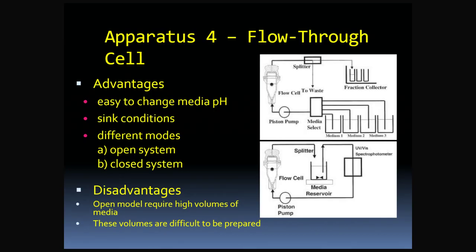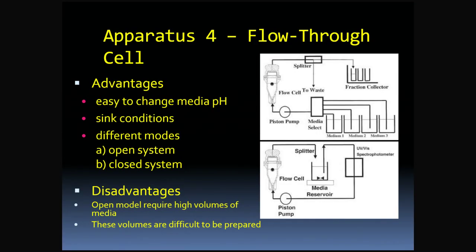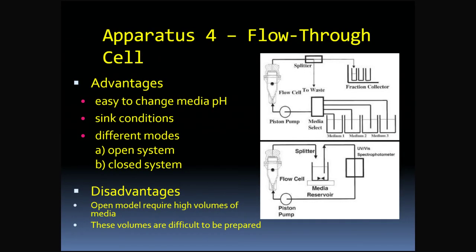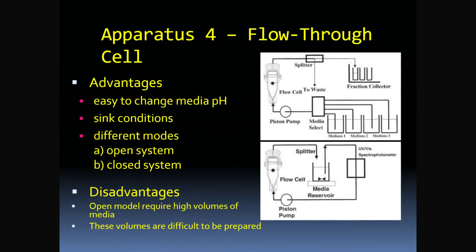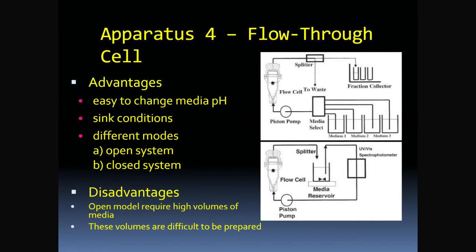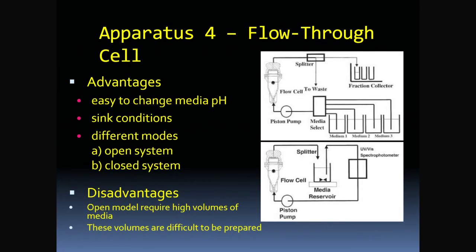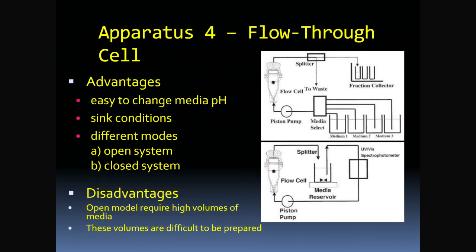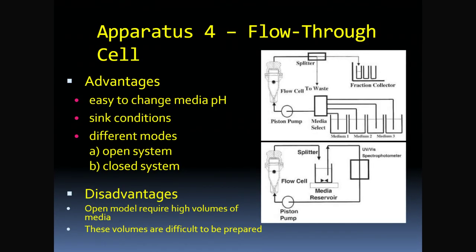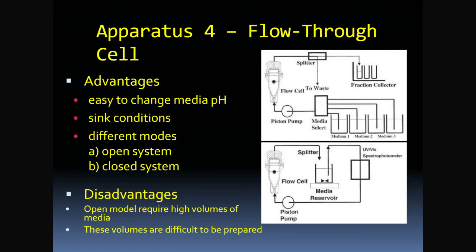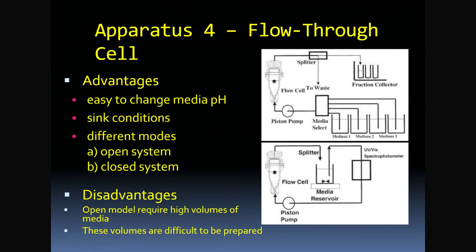In the open configuration, the continuous introduction of fresh solvent ensures that the concentration gradient, the mathematical difference between the drug's solubility limit and its current bulk concentration, remains at a theoretical maximum, essentially eliminating the risk of saturation. Notice the integration of the media select valve. This engineering feature enables precise, instantaneous pH transitions to simulate the sequential movement through the gastric and intestinal tracts. However, the open-loop model requires massive quantities of media, presenting a logistical challenge in maintaining the exact chemical composition of the large fluid volumes needed to drive consistent mass transfer.